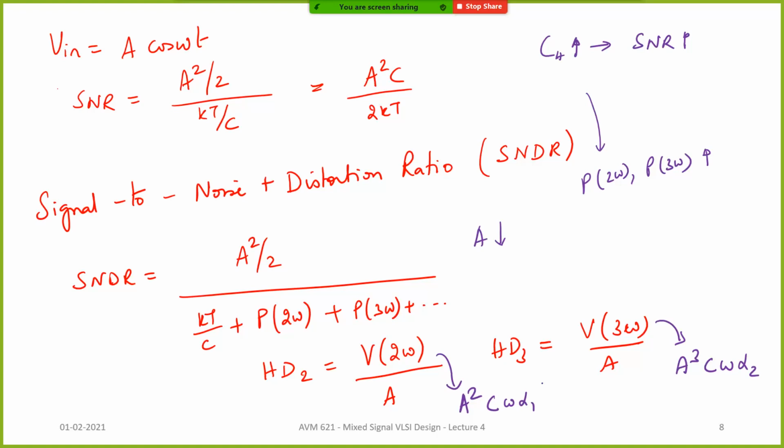You typically want your ADC to have the maximum range as possible, right? You can't tell others, okay, I have designed an ADC, but it's not really that good. Although my supply voltage is, let's say, 1.2 volt, you can work only up to 0.8 volt. Then people will say, I don't want your ADC, I will go to something else. But this is the way things behave.